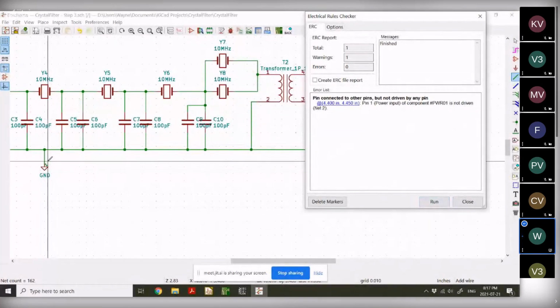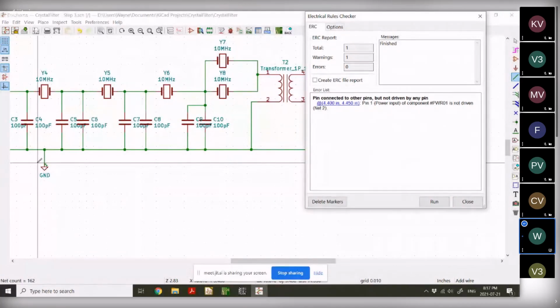This error here is actually saying it's a feature of KiCad. It's not quite smart enough to know where the power and ground connections are. The reason you have this in KiCad is most of the time your power is coming off board on something like, you know, a 1 of 10 pin connector. So you need to tell it which of the wires coming into KiCad, into the diagram, is the original power supply and which one is the ground.